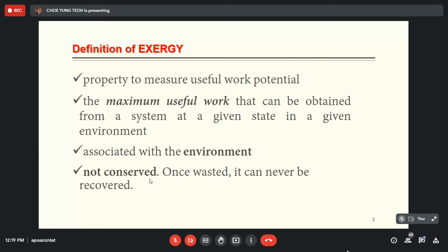That's why they came up with this definition called Exergy, where you can estimate the maximum possible useful work that can be done in this situation, not just by the temperature of the system. You still need to know the pressure, temperature, and variables of the surrounding.